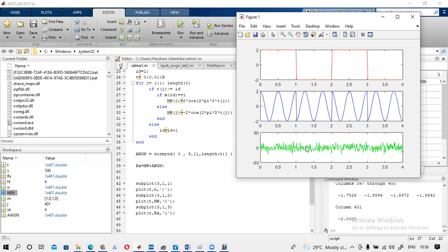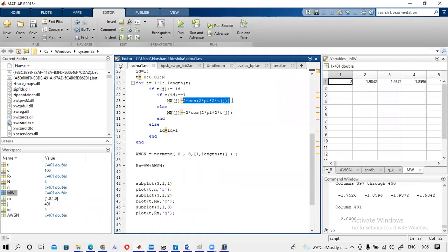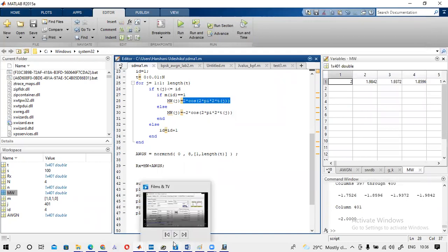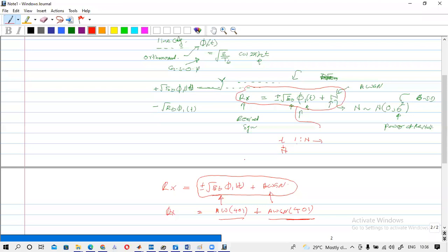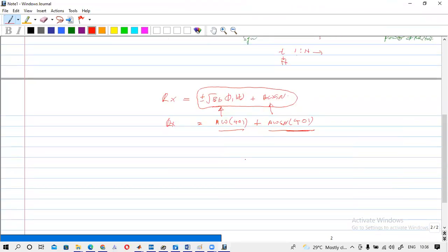What we are doing here is, we didn't change the power of the transmitted signal, but we changed the power of the noise. So this will be our transmitted signal, and that signal has some power. Let's say it is the signal power S, and here you have noise power also, let's say N. So this will be your SNR, signal to noise ratio.